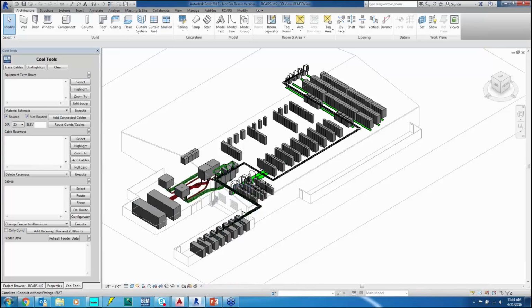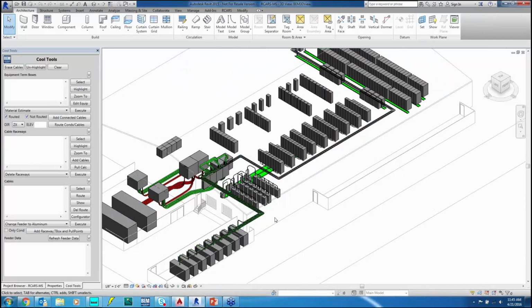And then we're going to drop out of these panels into a raceway subfloor cable tray so that we can feed power to all of our racks, from the UPS on this side and from the lighting panels on that side. Raceways have all been modeled in Revit.